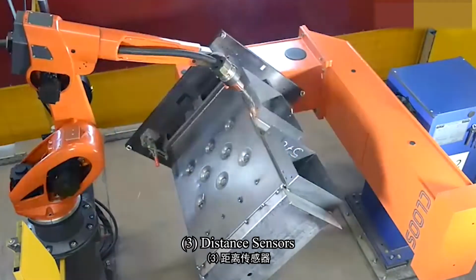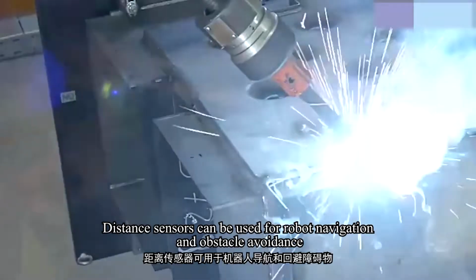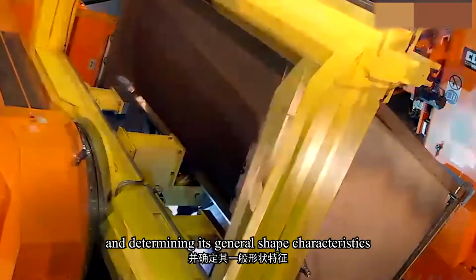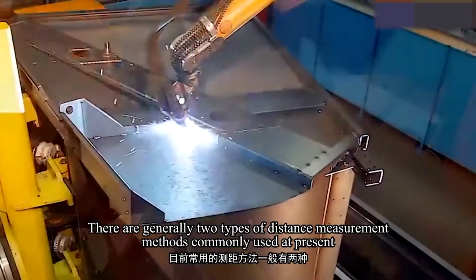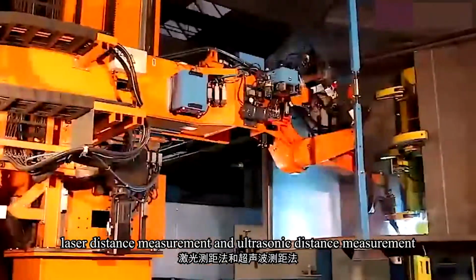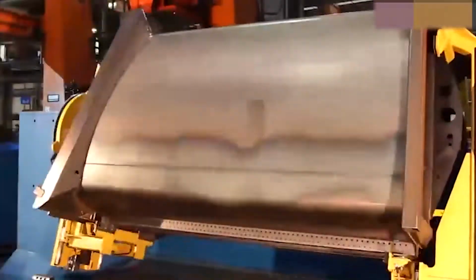Third, distance sensors. Distance sensors can be used for robot navigation and obstacle avoidance, as well as for object positioning in robot space and to determine its general shape characteristics. There are generally two types of distance measurement methods commonly used at present: laser distance measurement and ultrasonic distance measurement. 4.